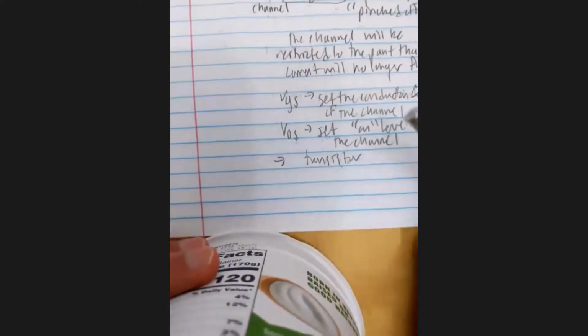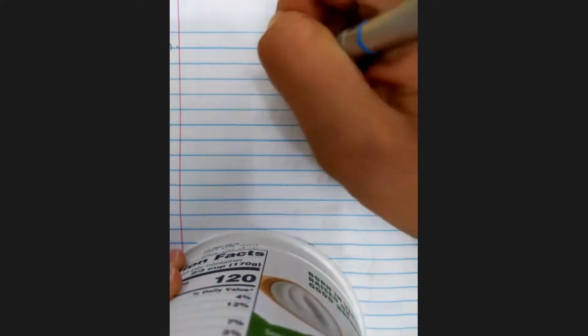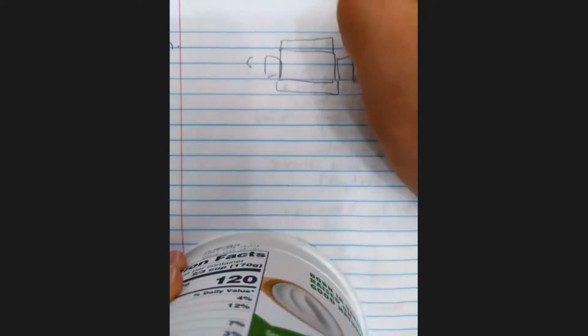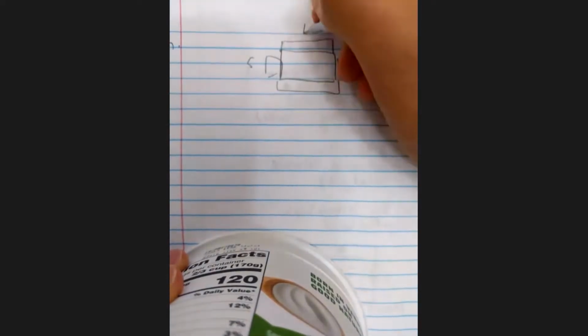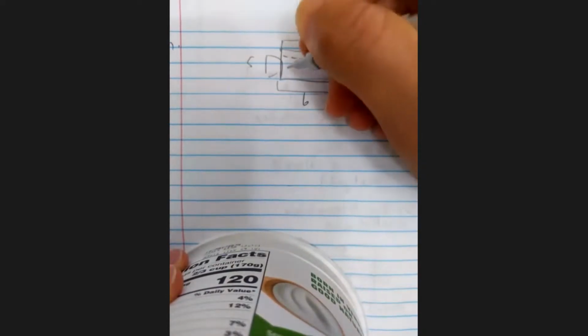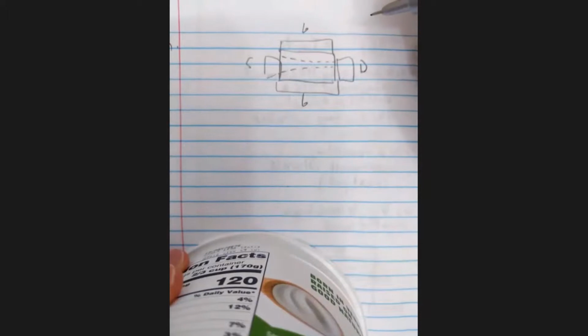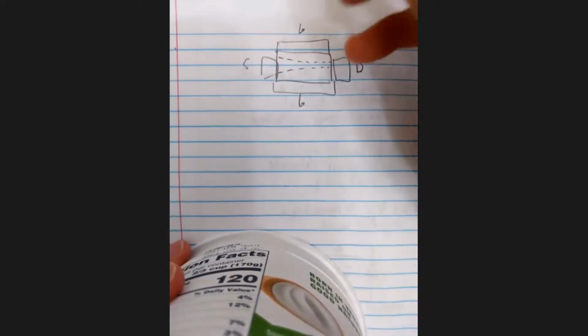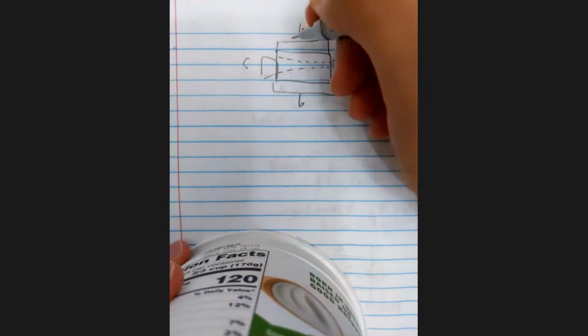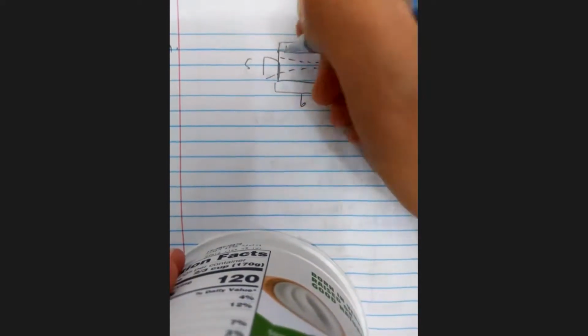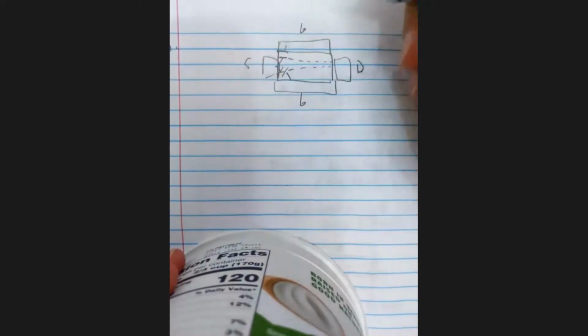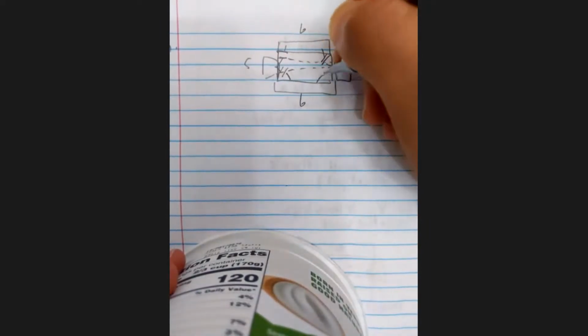Okay, so now in part H, we want to identify the physical origin of the capacitors in the structure. So this is kind of a long problem. So we're going to draw the sandwich again. And very quickly, we're going to note that I think the assumption is that we still have some VD being applied. So the depletion regions are a bit imbalanced, but essentially the causes of the capacitances in every case are going to be the depletion regions. So we have one here and we have one there.